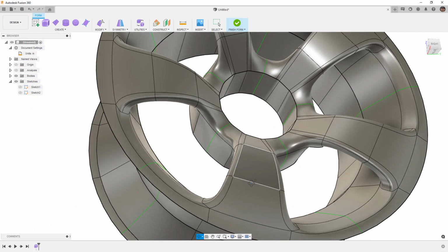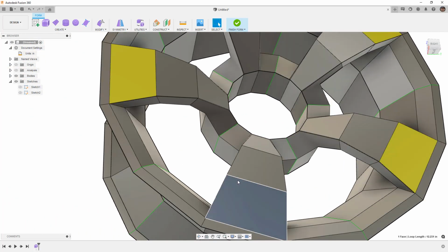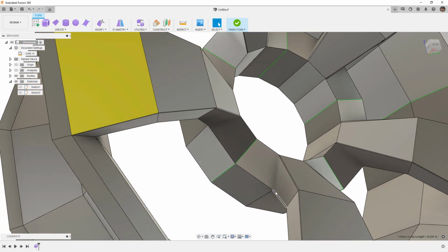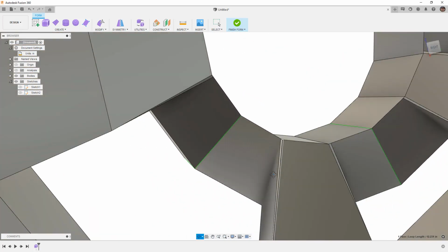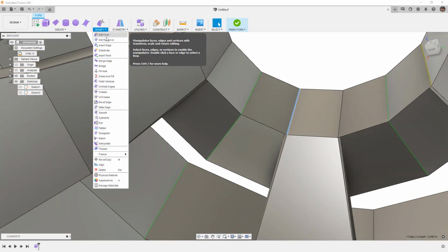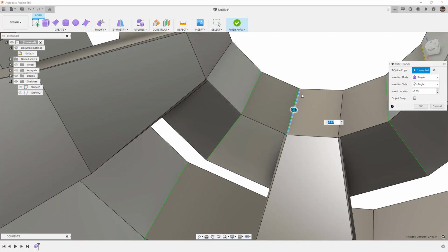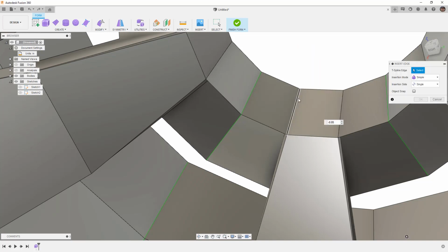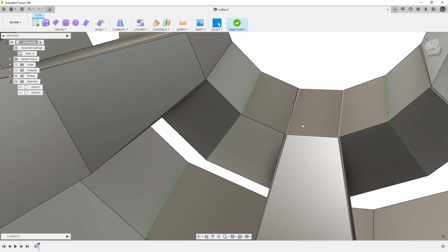And you'll notice now if I try to go back into box display mode, I've got that small lip that's added here. If I rotate this around, I've got the small lip that's added here. It carries all the way down to the center, but it doesn't carry down to the bottom, which means that in order to keep the curves and everything happy, I need to put one in here. And if it's on the wrong side, again, because the preview doesn't tend to work right now, we're going to make sure that that value is just positive.